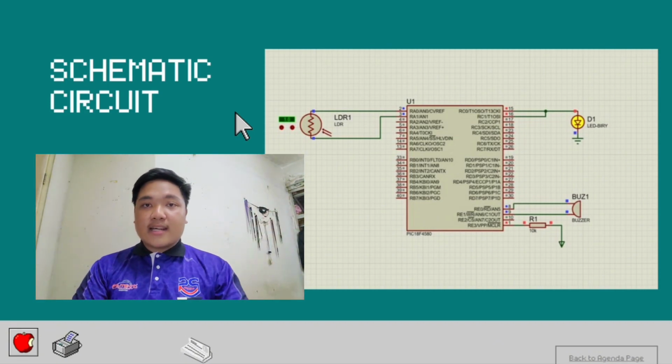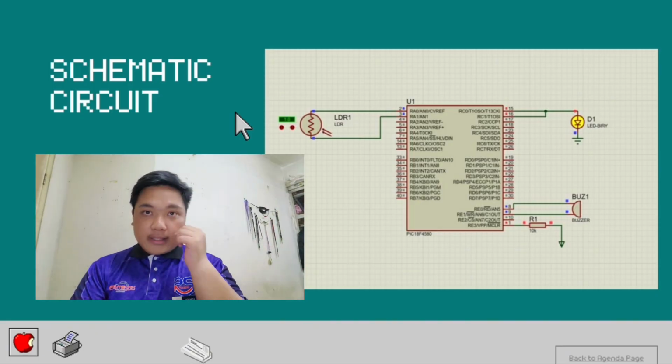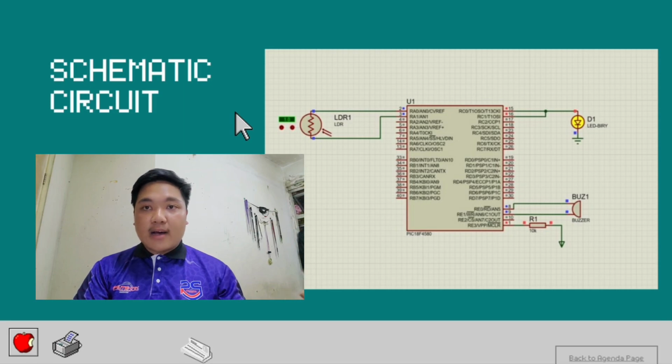So this is a basic LDR, light dependent resistor, based light detection system using a PIC 18F4580 microcontroller. The components and connections are as below. LDR1 is connected to the RA0/AN0 pin 2 of the PIC, and it acts as the light sensor. It works with a voltage divider using a 10K resistor, which we call R1, to provide an analog voltage based on light intensity.